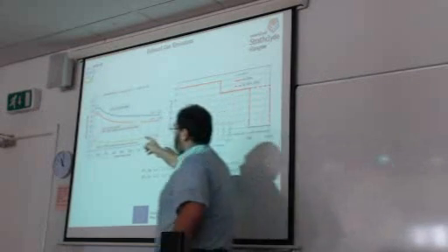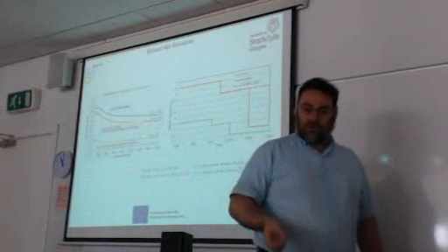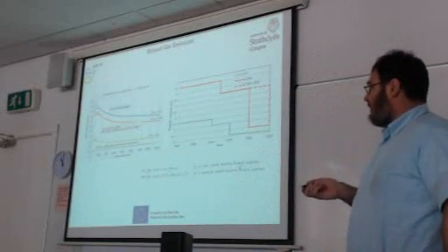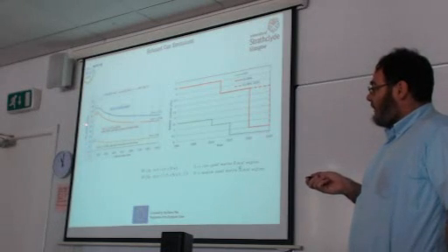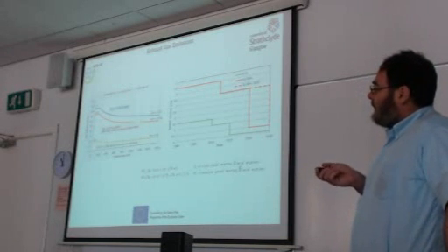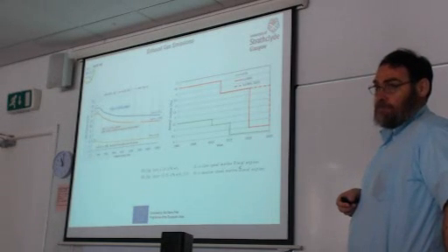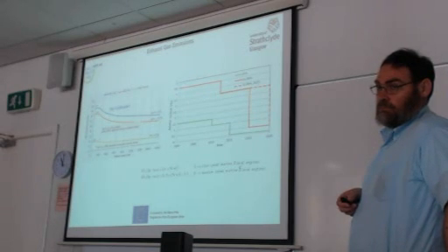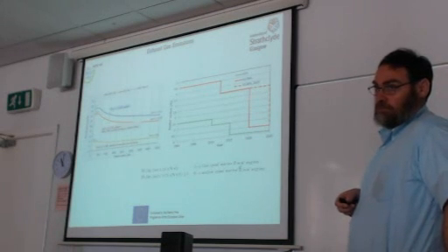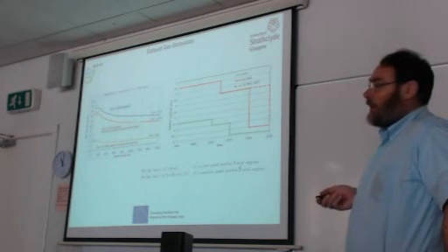I have an Excel file that we can discuss in the afternoon session as well, which is used to calculate emission levels and emitted amounts of constituents, depending also on the power. So we need to know that the absolute, or emitted, amount of NOx will be calculated by using the power as well. It's grams per kilowatt hour times kilowatt, which gives grams per hour, the mass flow rate of NOx.